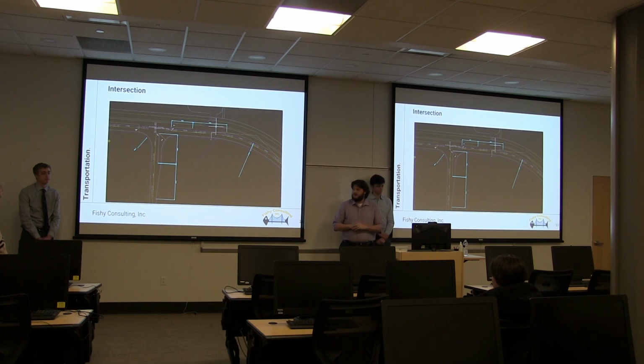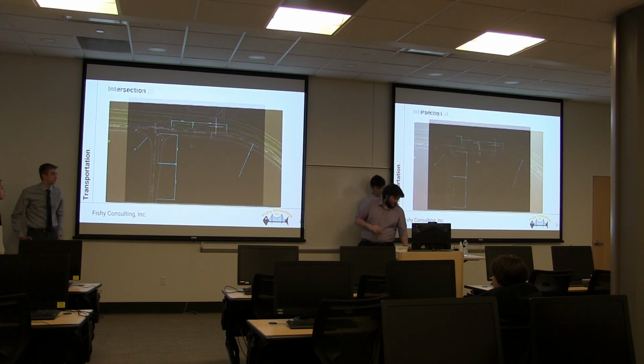Next, we have the intersection, a stop-controlled intersection with Old Oak Drive yielding to Ville Park Road. The turning radii are 50 and 35 for the entrance to the parking lot. All the taper and storage lengths came from the NDOT Design Manual, and there is no deceleration length based on the speed limits being pretty small, and the data we were given for the traffic was pretty low too. So we decided not to use deceleration lengths.